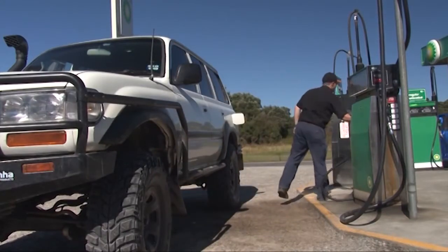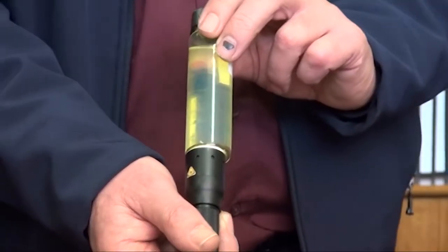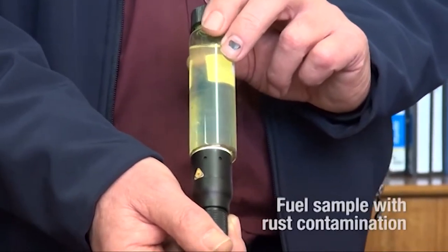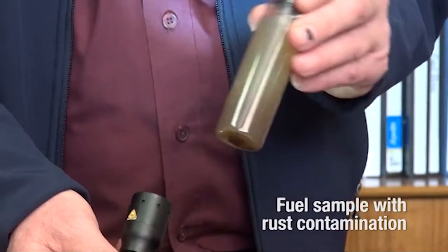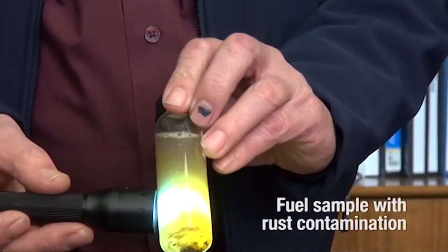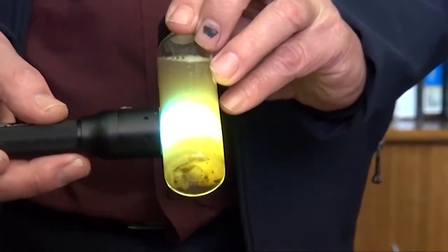Now, what does water do to the common rail components? Predominantly because of our high pressure and our high temperatures, rust is very prevalent. It damages the supply pump, rusting components, seizing valves. It causes rust in lines. The rail is susceptible to rust and ultimately seizes the injectors due to rust and also from the water expansion in the tip of the nozzle. No vehicle is less susceptible. Most common rail vehicles are quite susceptible to water damage.